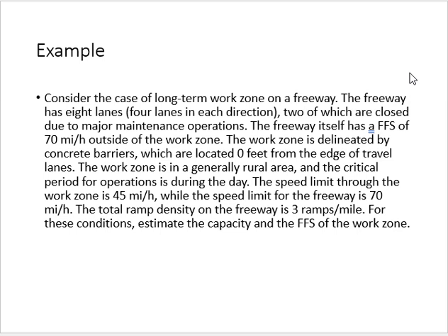Okay. Because of this 1 month, should I apply adjustment factor? Should I start applying adjustment factor? No, because rest of the 11 months are fine. Clear? So adjustment factors are not done for short-term conditions. Whether they are for weather, whether they are for incident, whether they are for work zone, anything. Okay, so that's why they mentioned in the question, it's a long-term work zone. Some projects take very long, right?